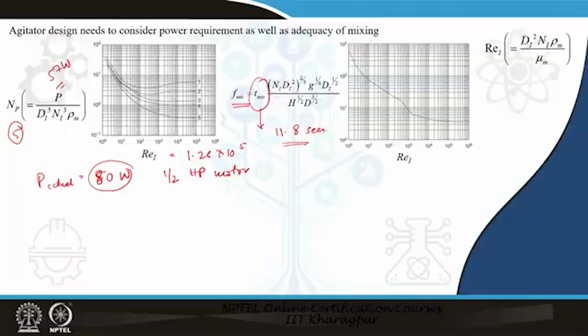For most cases we will find that a single stage will not be sufficient, we need multiple stages. Multiple stages can be provided by a number of mixer settlers in series, or more commonly by a continuous operation device, a packed column or a sieve tower. But the design of packed column and sieve tower for extraction and for distillation or absorption are completely different. So, in the next class we take up the continuous operation devices and discuss how to find out the number of theoretical stages, the diameter of the column, etc.